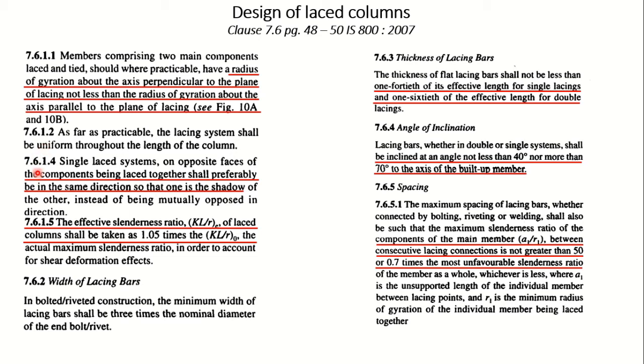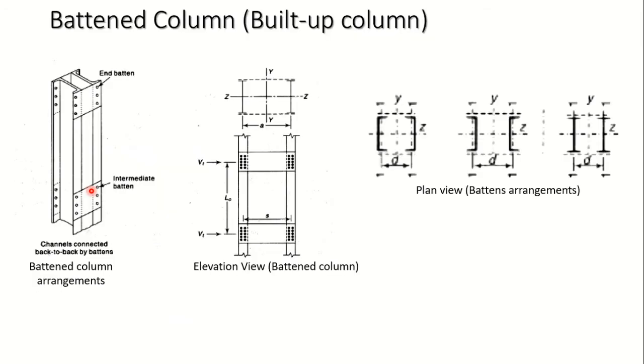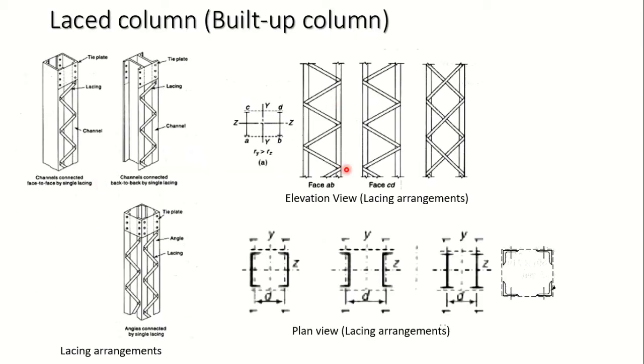Then, single lacing systems on opposite faces of the components being laced together shall preferably be in the same direction. That is, face AB and face CD. These are the two faces you can see here. If you observe, they should be in the same direction.